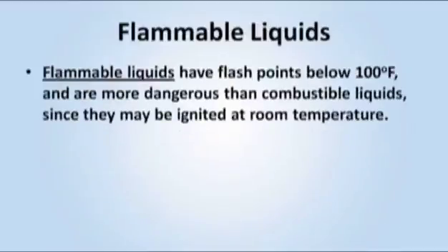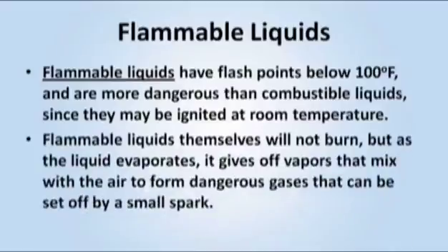Flammable liquids have flash points below 100 degrees Fahrenheit and are more dangerous than combustible liquids since they may be ignited at room temperature. Flammable liquids themselves will not burn, but as the liquid evaporates, it gives off vapors that mix with the air to form dangerous gases that can be set off by a small spark.